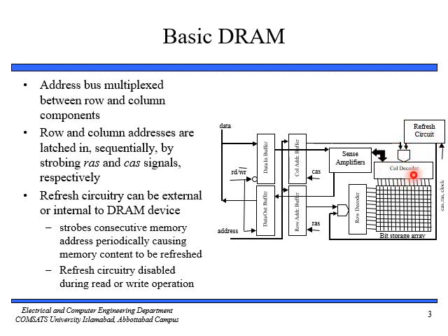So this is the column decoder, this is the row decoder, and we are not refreshing every time, that's why we are using a mux here, multiple lines and a single output. Sometimes when we are refreshing, we are not reading and writing. When we are reading and writing, we are not refreshing. So this is the basic architecture of the DRAM.